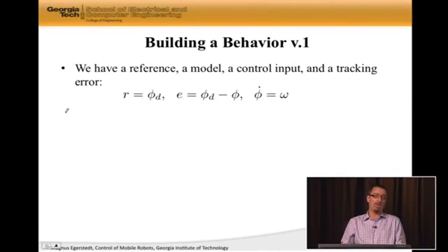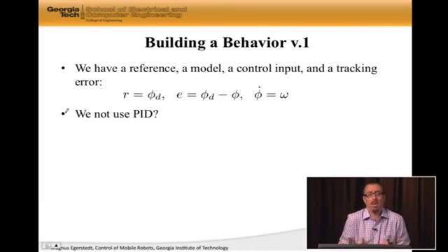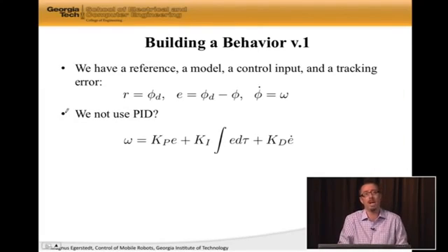So we even know how to design controllers for that. How should we do that? Well, we saw PID, right? That's the only controller we've actually seen. So why don't we try a PID regulator? That seems like a perfectly useful way of building a controller, right? So omega is Kp times e, where Kp was the proportional gain. This responds to what the error is right now.